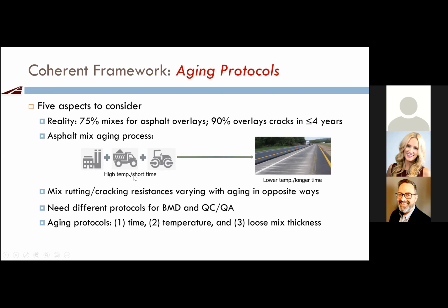So here we're talking about short term and high temperature. That's what we have to address when we're talking about the aging protocols. Meanwhile, after the placement, going into service years, we're talking about much lower temperature compared to the construction, and a much longer time. So we need to address both production and placement, and also the long-term performance.